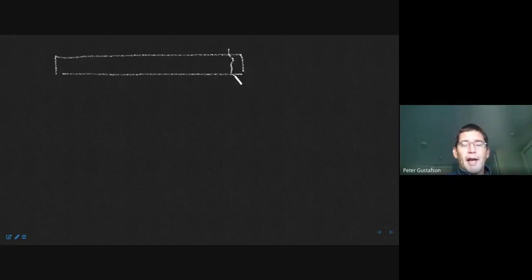So keep in mind what these are. These are differential equations that govern the beam deflection within the beam. Okay, within the beam is an important statement there. So what you've described is a boundary condition. It's the shear on the right-hand side. So if we wanted to examine that, that would be a great thing to examine. We could take a free body diagram. So if this is the entirety of the beam, we could draw a free body diagram essentially by taking a cut there.